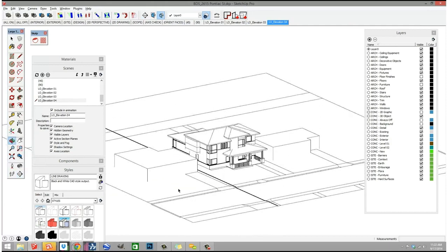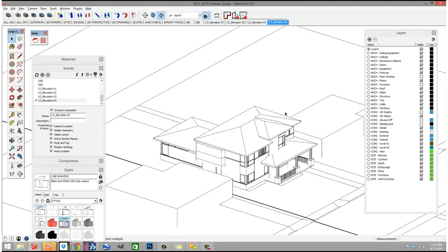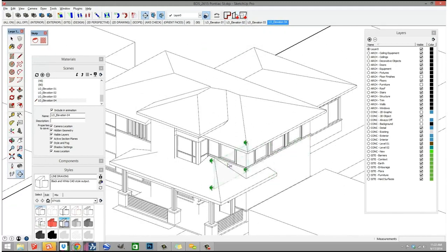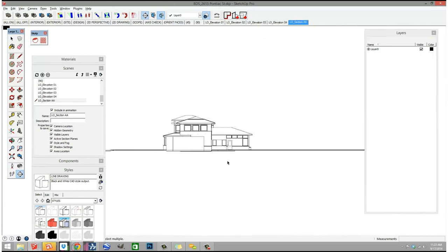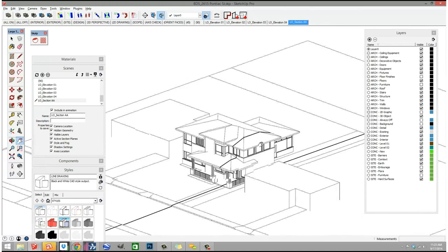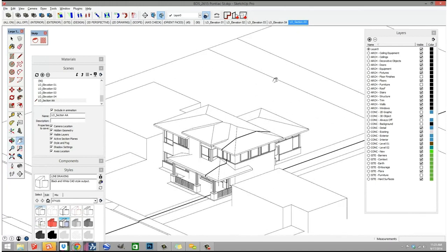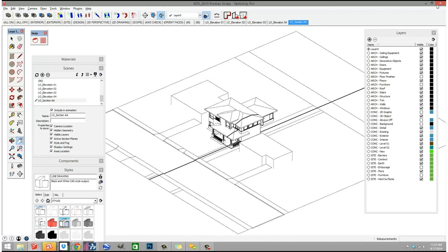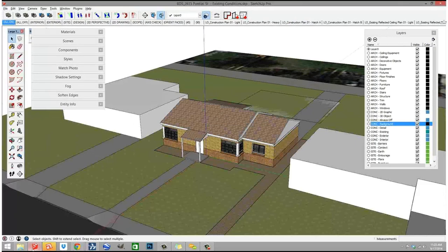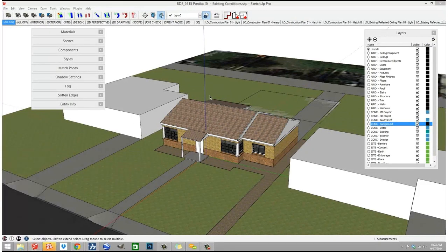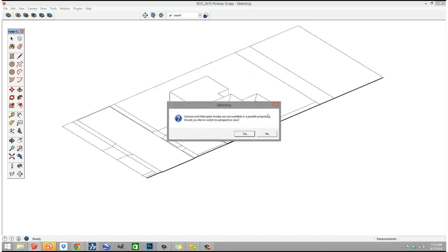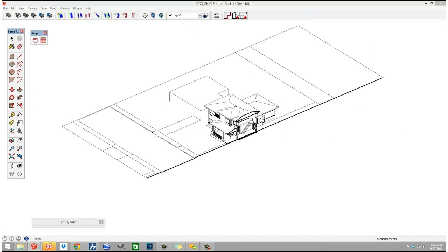All right, so now we've got that all set up, and now we want to add some section planes. So I want to cut a section through this. I know that this space is a little bit interesting here, so we'll just drop that right on that window, and look at what that does. It throws our section plane in, and let me close this and save this, and then we're just going to reopen it. I've got something goofy happen with my graphics card, so we'll just redo that, and we'll keep on moving forward. There's section AA. Okay, so there's our section.